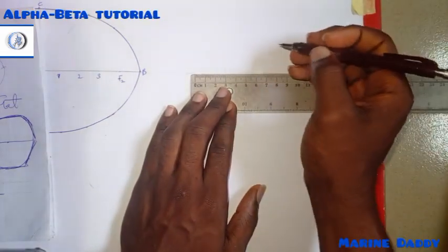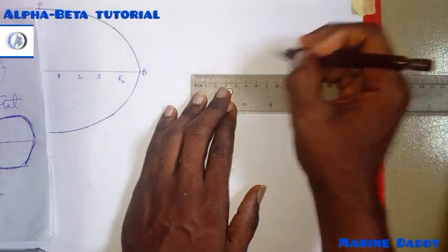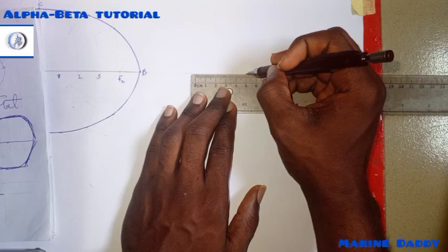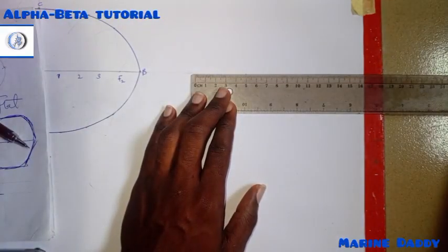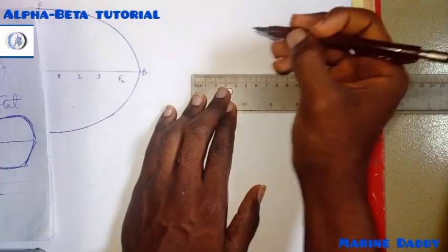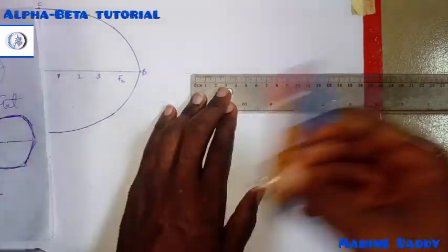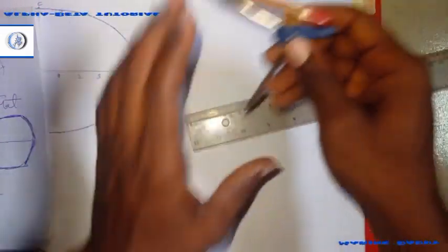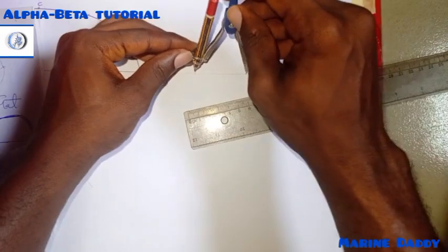So we'll draw a straight line. After I draw a straight line, since they say the distance across corners is 10, and I explained earlier that when you hear distance across corners, they're talking about the diameter, and we want to draw a circle, so we need a radius. That's half of the distance across corners. Since they say it's 10, we are making use of 5.